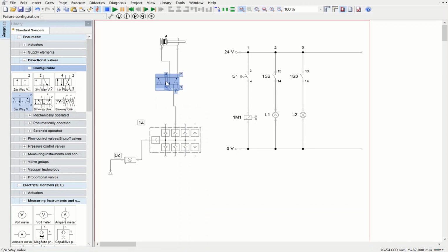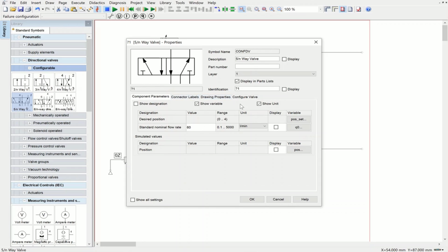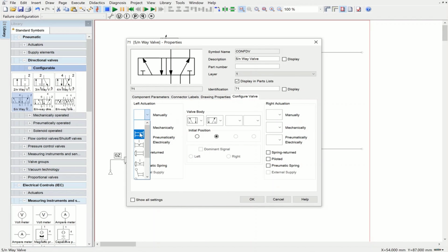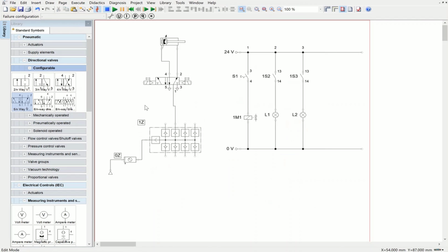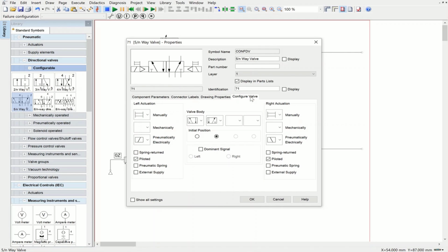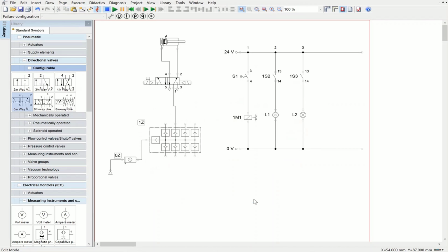And we have to configure this. I'm going to put the manual override 2, the manual override, and then electric actuation, and it should be pilot 1. And the same thing here, right? Pilot, and we can put the manual override 2 if you want, and hit OK. Or just one side should be fine. So I'm going to remove the second override that I put there. So that side is going to be this electrical actuation. Hit OK. Now we have almost everything set in this side.